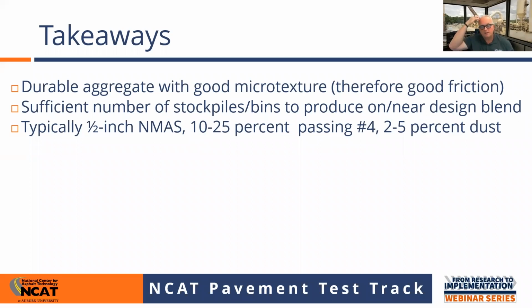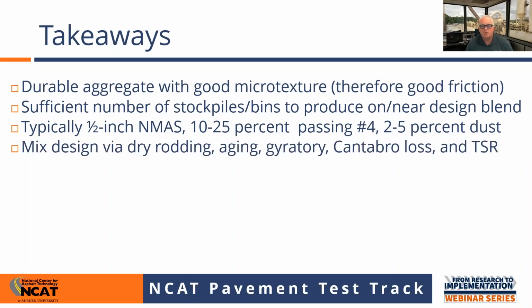And here on the test track with our trucks and with our loading, the typical OGFC after 2 years of our fleet operations, we've got about 20% of the permeability that we started out with, but we still have great spray reduction. So you're going to lose a lot of permeability, but safety is still going to be greatly improved on the roadway. So that's a good reason to look at those smaller mixes, because you do have better sustained permeability over time. And looking at design, maybe you even get some better quarry options for putting that mix together.